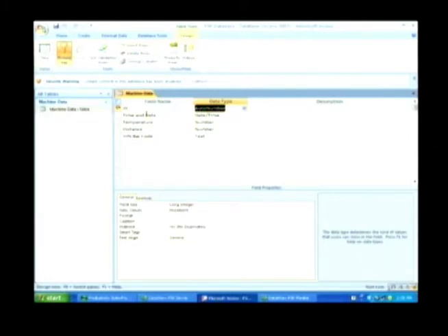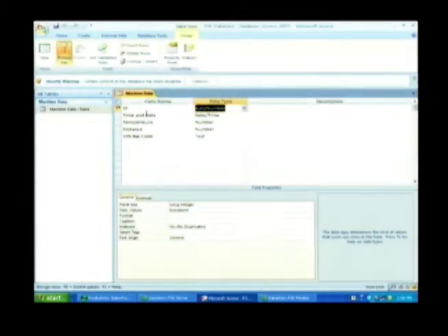Then there's also a DataWorks monitor that allows us to connect to the server, and we're going to configure the DataWorks server. Within the monitor we're going to create a device procedure, and we can create dozens or hundreds of different procedures for what we want to do with the data. Then from there we'll export the procedures to a configuration file that we'll be able to use back within the Productivity 3000 software that will allow us to create a DataWorks request. And then finally we're going to test it.